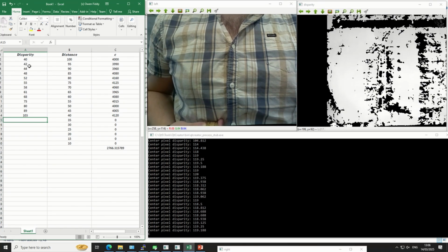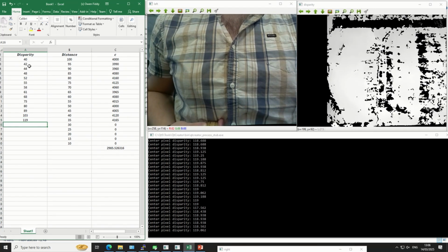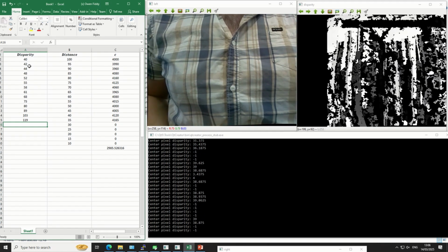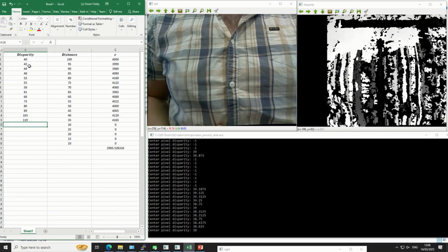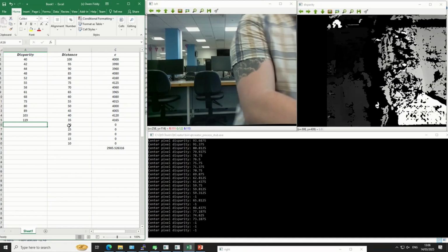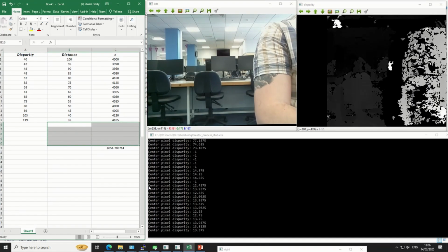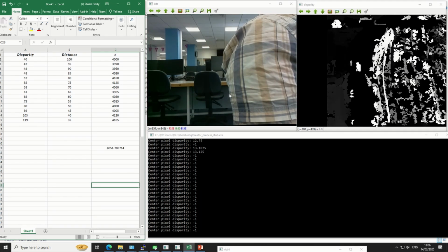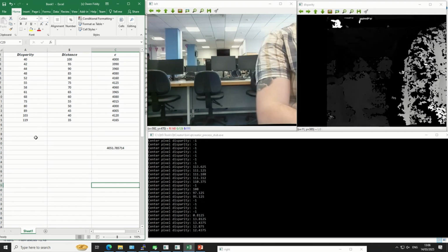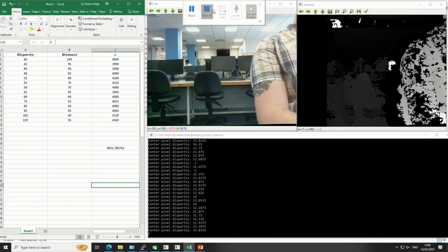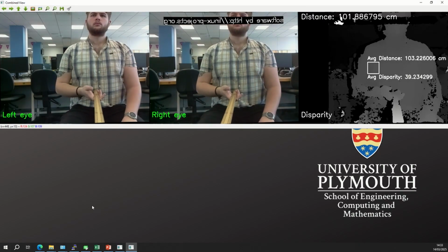distance we're looking for. As we're looking for things between 10 and 100 centimetres, we get a good average disparity that helps it be accurate across this range. It may not be perfect for close range or far range, but over this whole 100 centimetres, it should be good. It should average out a lot better. And in my testing, it actually resulted in a much better system, as overall it reduced our errors to only 3% rather than over 15%.